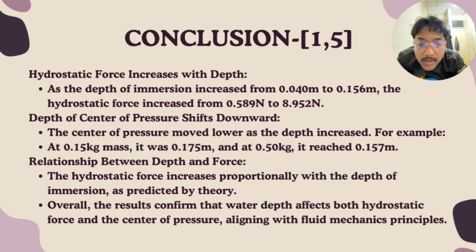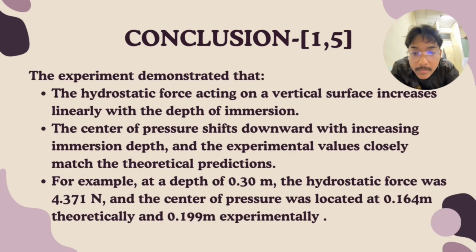Relationship between depth and force: the hydrostatic force increased proportionally with the depth of immersion as predicted by theory. Overall, the results confirmed that water depth affects both hydrostatic force and the center of pressure, aligning with fluid mechanics principles. Next, the experiment demonstrates that the hydrostatic force acting on a vertical surface increases linearly with the depth of immersion. The center of pressure shifts downward with increasing immersion depth, and experimental values closely match the theoretical prediction.